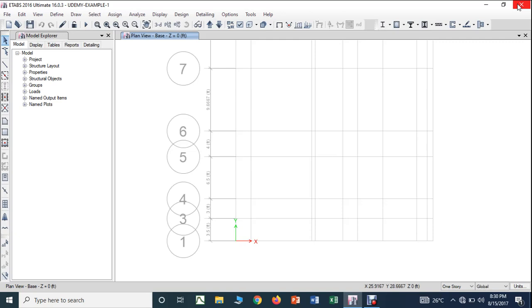Due to the advancement in the metallurgical process, nowadays people have started using the Fe600 grade also. Fe600 grade steel, that is characteristic strength equal to 600 Newton per mm square, is also available. But it is not widely used; we still use Fe415 and Fe500.